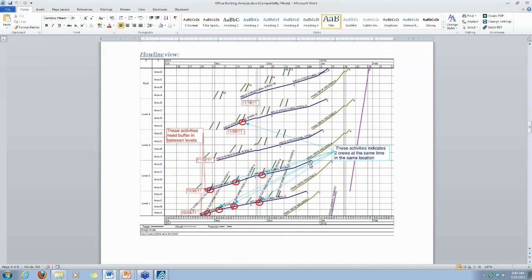In addition to that, general LBMS theory, flowline theory states that if you're going to be calculating an exact duration for what you think the task is going to require to be installed in a certain location, that may be affecting some of the float calculations that you had in your CPM schedule. And so part of our process for optimization as well is to suggest that we input some buffer or some time between activities where we perceive there to be a bottleneck or some handoff risk as a way to reintroduce the float back into the schedule in a designed way.